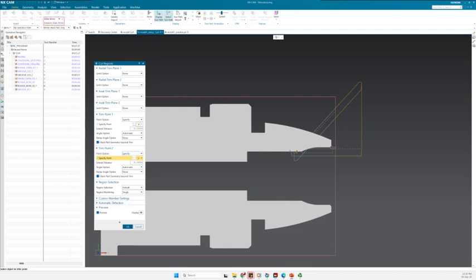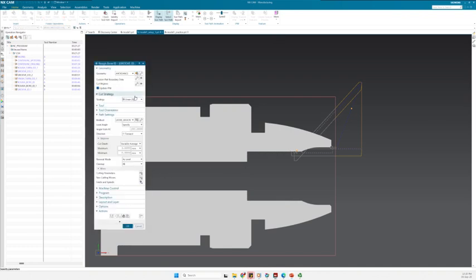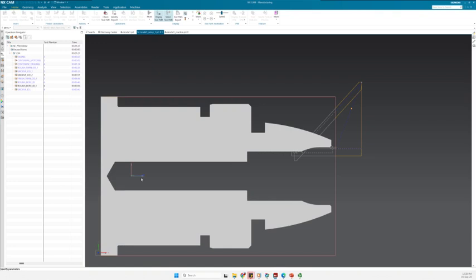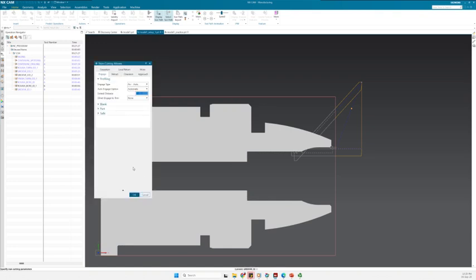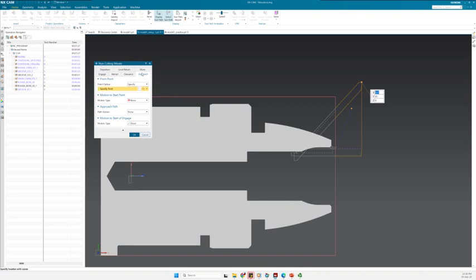And then let's see if I need to actually change the non-cut movement. It looks like, because I can see that it's already colliding here, I can go to this non-cut move, then I can go to the approach. So here I have the approach, then motion to start, I can change it to radial to axial maybe.